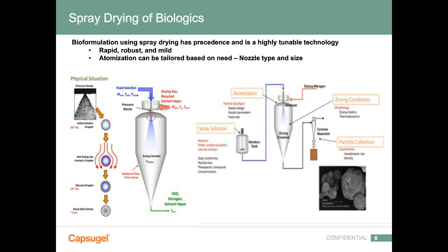And then again, utilizing this general holistic model of spray drying itself, you have the individual components that you're worried about when spray drying. So you have typically an aqueous solution that has water-soluble excipients, and a variety of different actives that are associated with this. The atomization itself is putting on a little bit of shear stress.